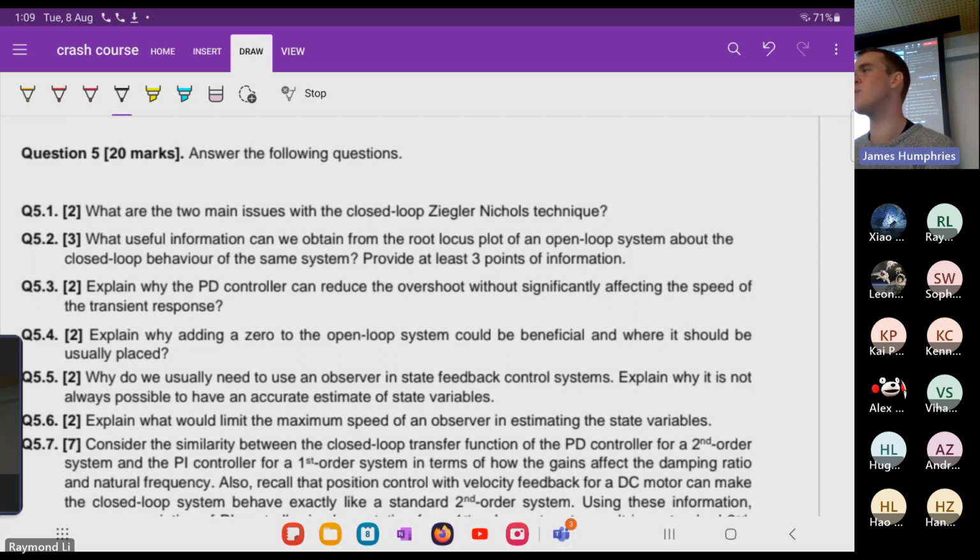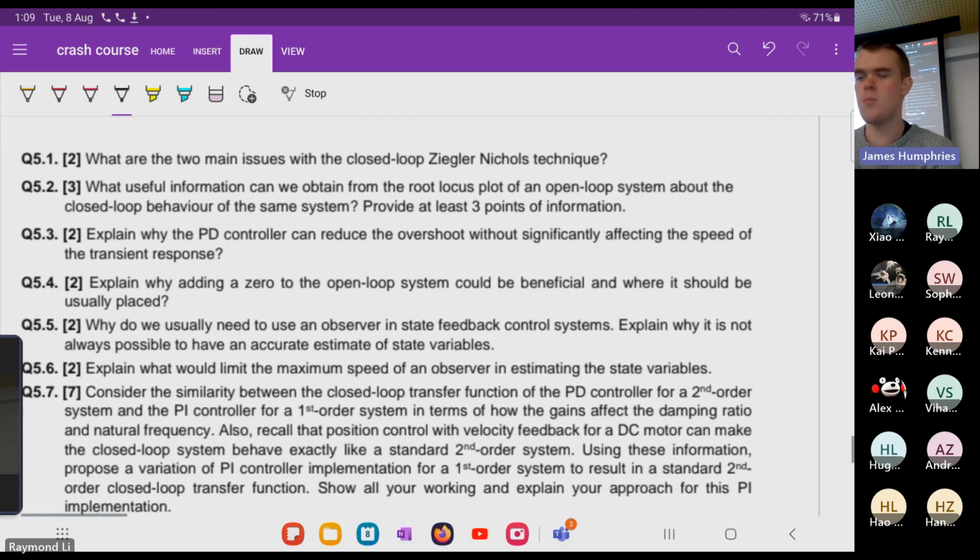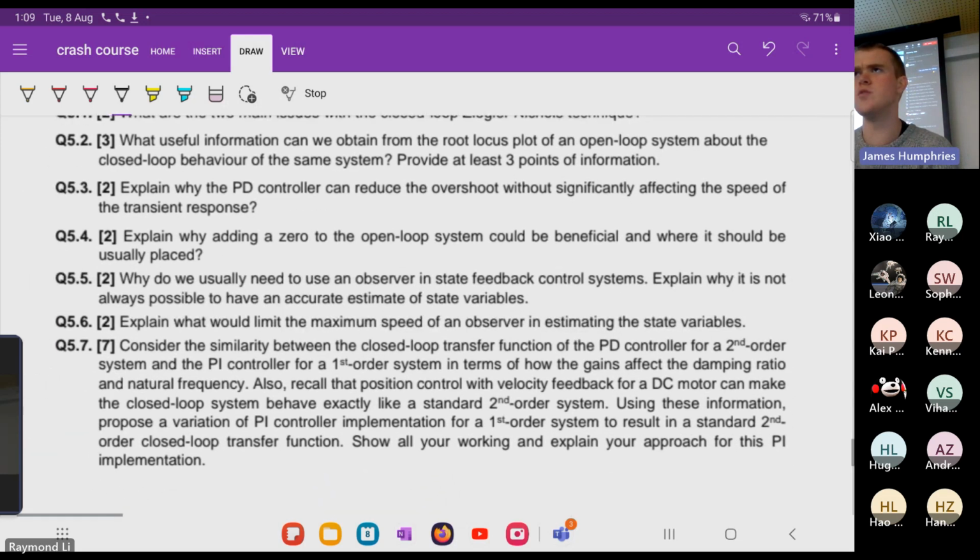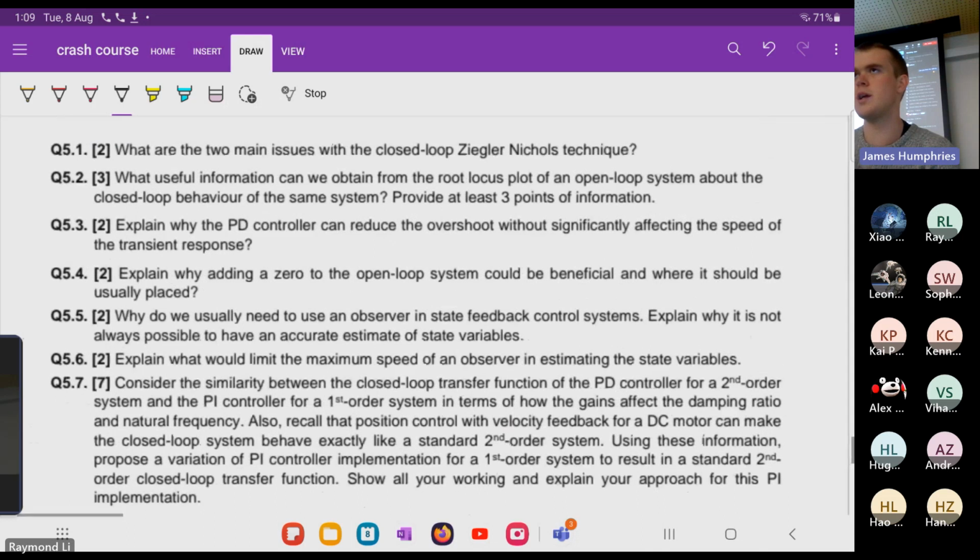The reason I say that is because pole placement is literally where you go, I want a pole in these two spots to get this percentage overshoot and settling time. Then you set the other ones 10 times further away, you end up with those equations, and what we've been doing earlier, where you then match coefficients. We effectively did it for the K1, K2 values, if you remember. But I don't really expect you to remember Ackermann's formula, because you just plug it into MATLAB, and MATLAB tells you what it is.